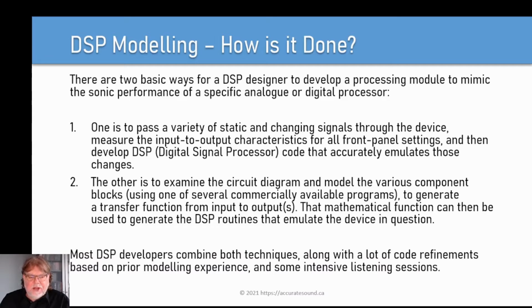The other is to examine the circuit diagram and model the various component blocks using off-the-shelf software to generate the transfer function from input to output. That mathematical function can then be used to generate the DSP routines that emulate the device in question. Most DSP developers combine both techniques along with a lot of code refinements based on prior modeling experiences and some intensive listening sessions.